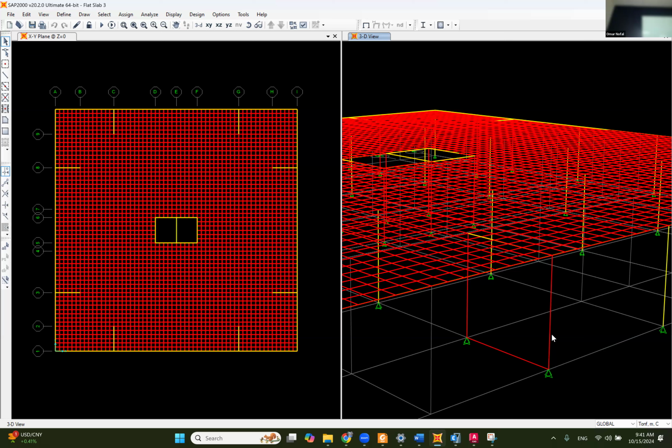So for example, say that you divided this wall into mesh size 0.5 by 0.5, but somehow, by the way, if you guys remember, when I divided it into 0.5, I didn't make it exactly 0.5 by 0.5. I told the software the maximum size is 0.5 by 0.5. So I'm not sure what is exactly the size of the mesh. Maybe 0.4, maybe 0.45. So if I divided this with a maximum size 0.5 by 0.5, this doesn't mean that it's going to connect with this one. What I want to make sure is I need to divide this in a way that can connect with the same size of the slab. Okay, that's a very, very important modeling aspect when it comes to finite element. You have to take care of this.